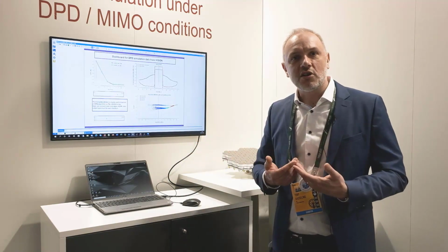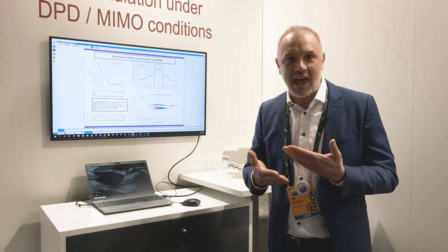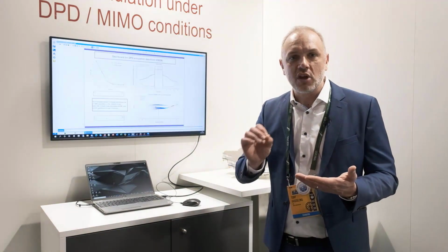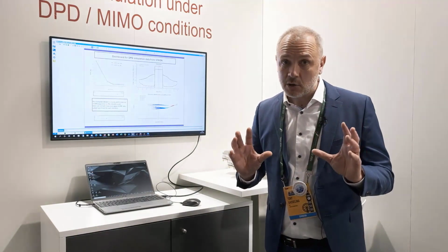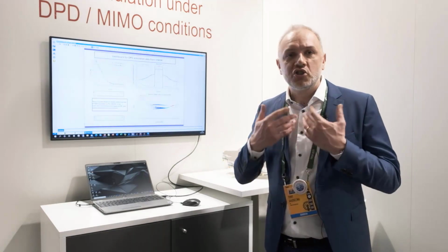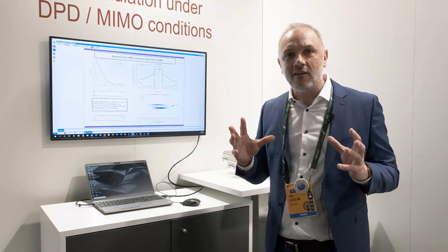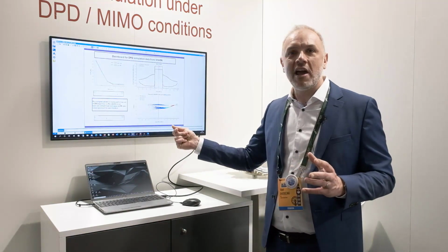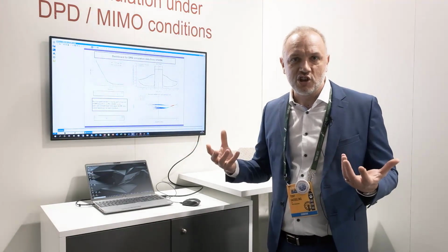And because of that, you can simulate, for example, in a circuit simulator such as ADS from Keysight, different biasing circuits of your power amplifier. You generate the data, and then you take this data, you forward it to the modeling tool, you will extract your behavior model, and you will simulate in real time what will be the optimized performance with digital signals.